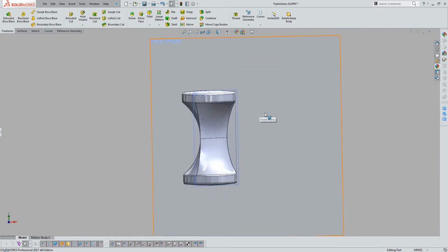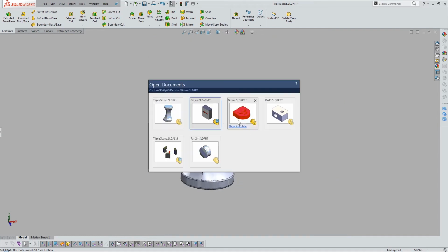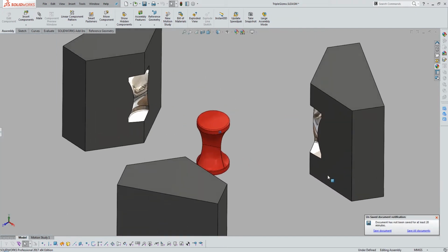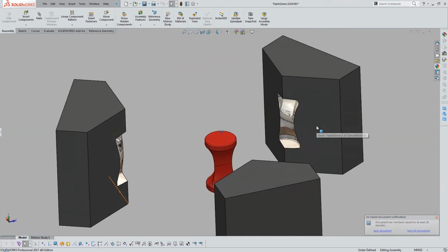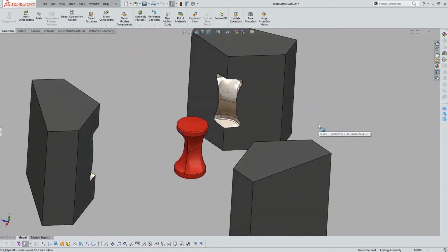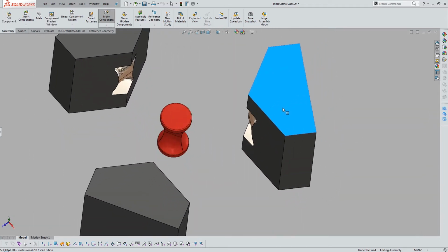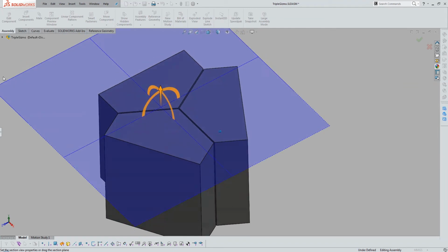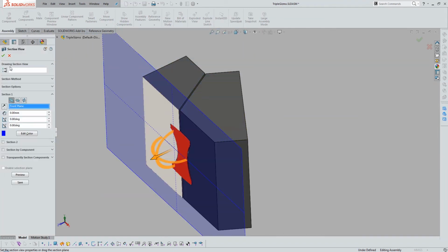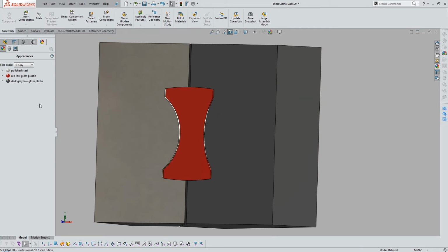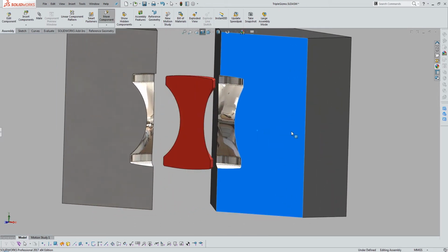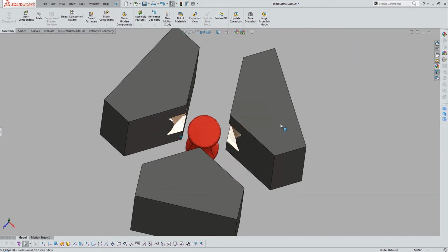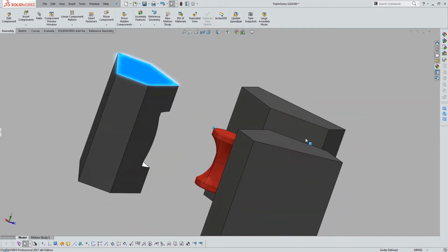So what I can do instead is use 3-part tooling. Now this isn't something that we try to accomplish with molding right now in class, but just know that as designers you have this option open to you for parts that require it. You can create tooling with more than just 2 pieces. Some surprisingly common items are actually created using some really complex tooling.